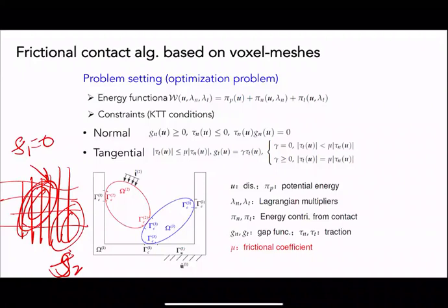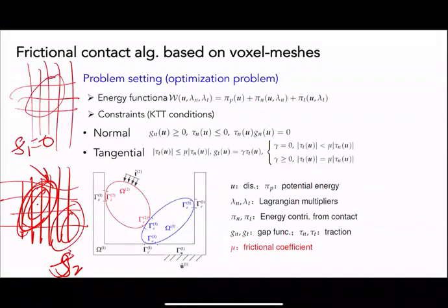If it's negative, we know this is inside the individual particle. The advantage is that we don't need to mesh the elements, because the level set indicator functions are stored in the entire grid as a scalar value telling us where the particle is. So the meshing issue is resolved.